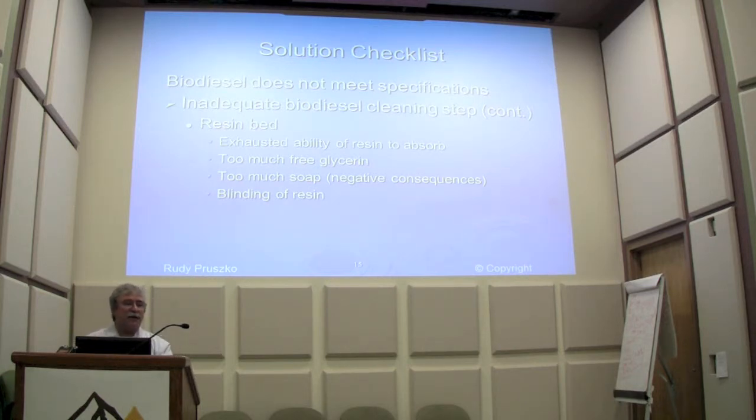After the dehydration, after our water wash. The other thing is, there are resins that can take out some free fatty acid. So if you had a batch that was just barely out of spec, sometimes you can bring it back with special resins. It'll take out some of the free fatty acid. Did you have a question?